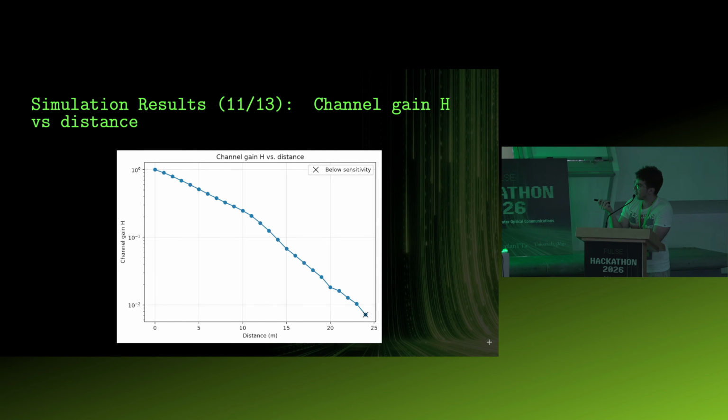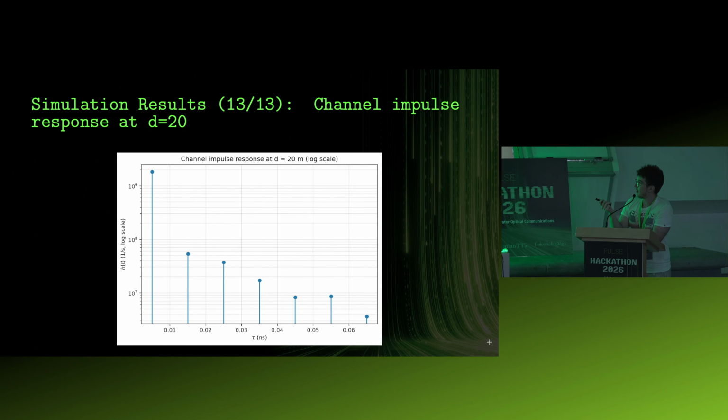This is basically the same graph. And this is the channel impulse response that we have utilizing the ray tracing model only, in this case 20 meters, and these delays that we have here are taken into account by computing the distance between the unscattered ray, the photon that reached the detector unaffected by scattering, and the received photon that we got.